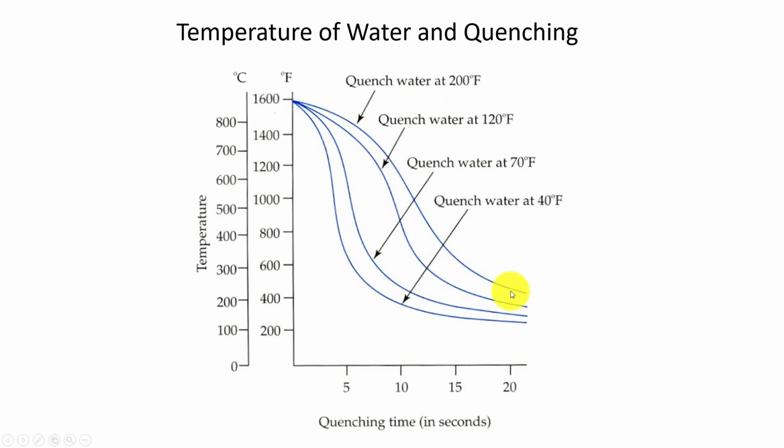So maybe I need to have a circulatory pump that's circulating water through a radiator and extracting that heat to maintain it maybe at room temperature here. Okay. So that could change as the process changes, my water temperature changes. Very important to keep that quenchant media the exact same rate.